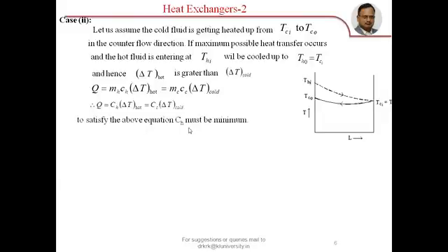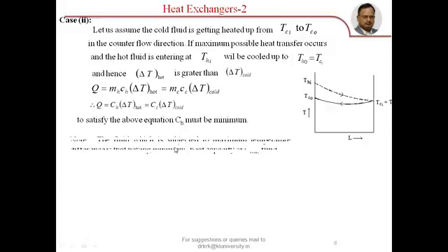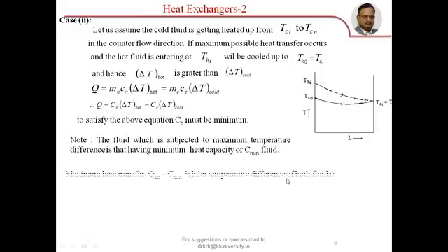So to satisfy this equation, the minimum heat capacity fluid should be MHCH, the hot fluid. So that is what I said. The fluid which is subjected to maximum temperature difference is the one having minimum heat capacity, or C minimum fluid.